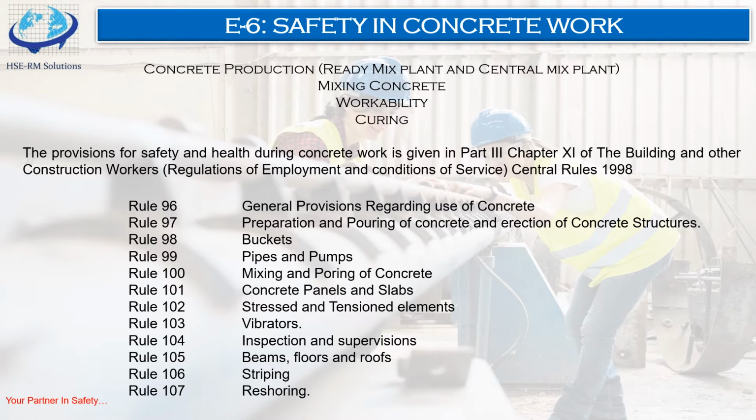Now workability, how is the workability here? Workability is the ability of fresh concrete mix to fill the form or mold properly with the desired work, with vibrations and all, and without reducing the concrete quality.